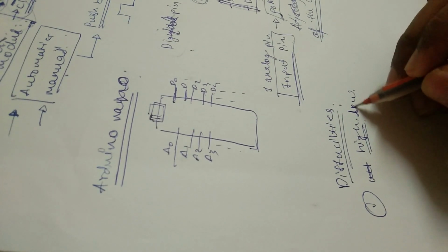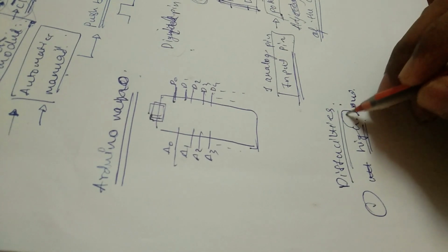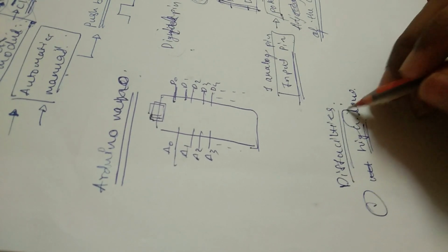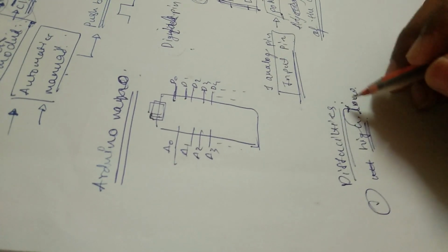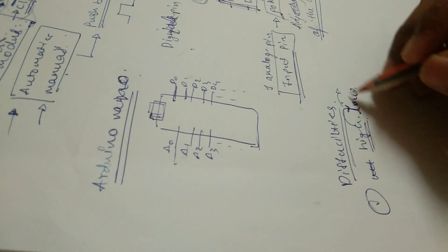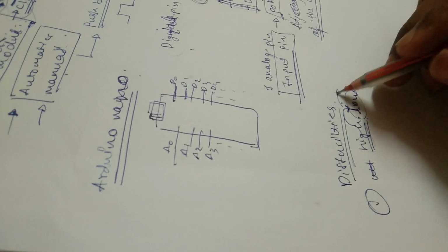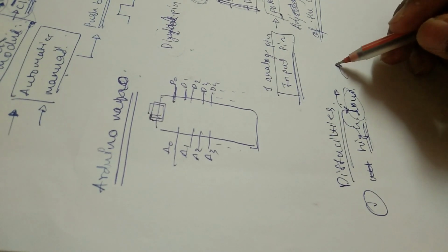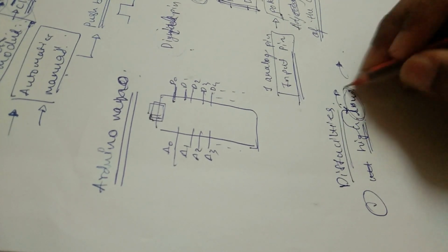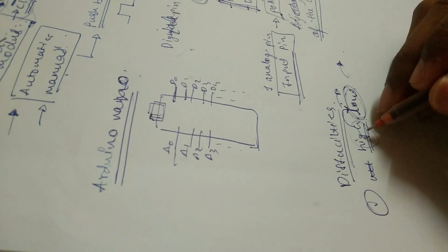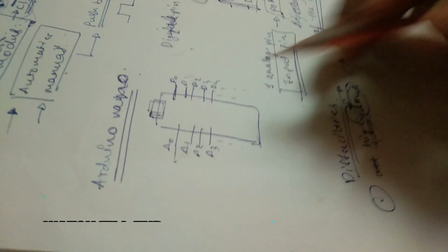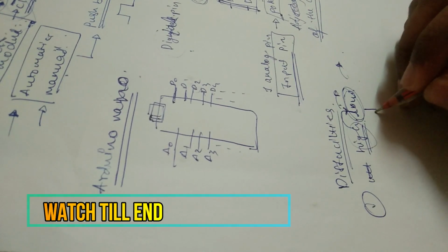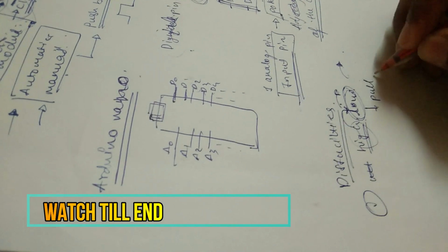As the pin goes from high to low, the microcontroller doesn't make it low enough for the further logic ICs to read it as a low signal at the digital pin. So we will need a pull down resistor here.